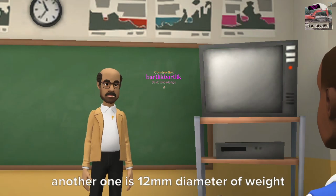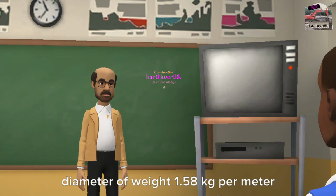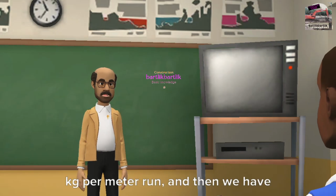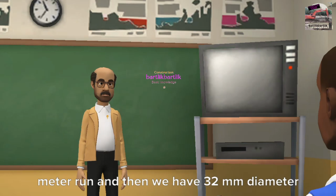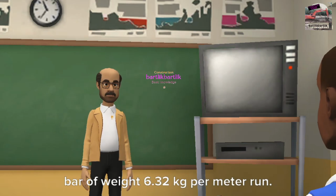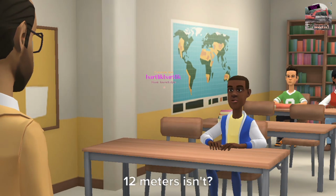Another one is 12 mm diameter of weight 0.89 kilograms per meter, followed by 16 mm diameter of weight 1.58 kilograms per meter run. Next is 20 mm diameter of weight 2.47 kilograms per meter run. And then we have 25 mm diameter of weight 3.86 kilograms per meter run. And then we have 32 mm diameter bar of weight 6.32 kilograms per meter run. Well captured, sir. But Mr. Bardlick, the length for the reinforcement bar is normally 12 meters, isn't it?